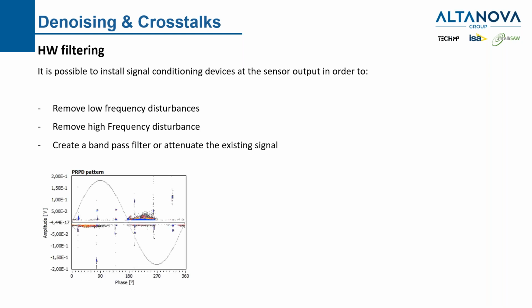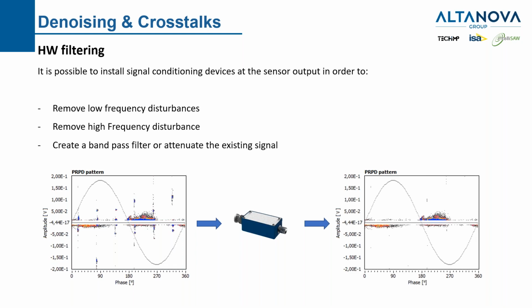Here we have a case with a full acquisition where we have PD and exciter noise together. If we make this signal pass through our hardware high pass 2.5 MHz filter, the signal will be clearer. We have lost the frequency components lower than 2.5 MHz, sorry, but we will have all the rest very highlighted. This is very important, in my opinion, if you want to correlate amplitudes. We shall measure the proper amplitudes, not the exciter amplitudes.